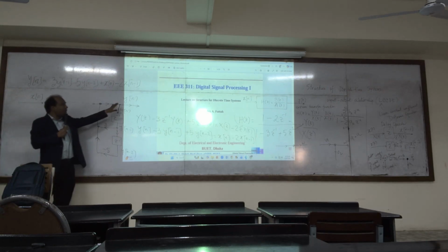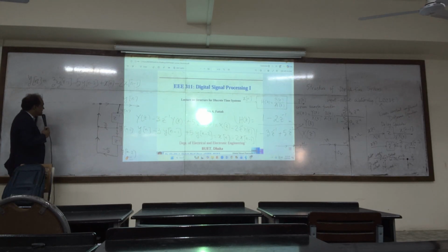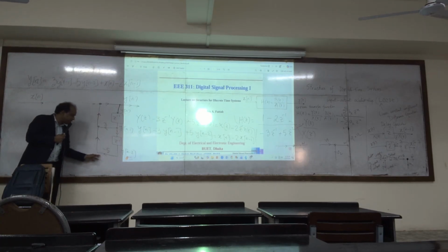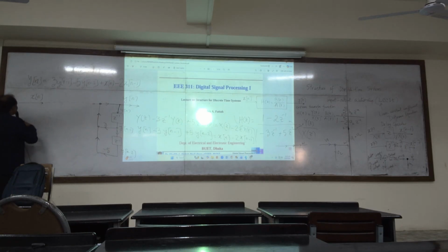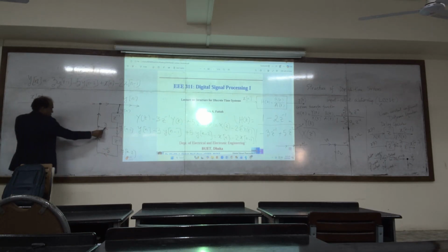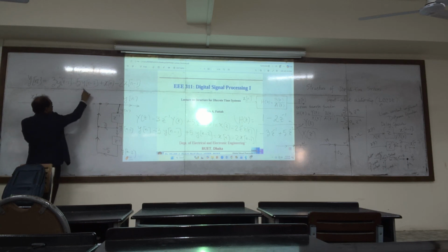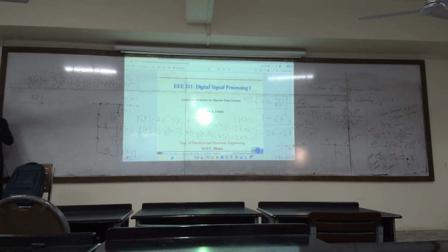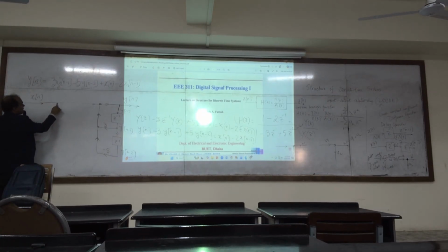So now you are close to your output, y(n). At this moment, y(n) is equal to x(n) plus 3y(n-1) minus 5y(n-2). I just need one more term, x(n-2)... x(n-1). So use exactly a z inverse and bring it here.